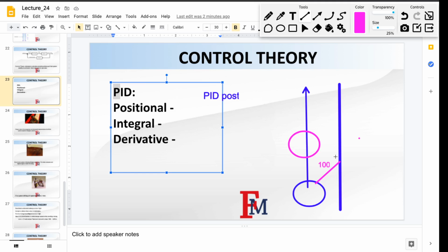Okay, and you're going to sense the wall again. So if you sense 125, for example, that means you moved about 25 to the left, right? So for some reason you moved over there, and that's not what you wanted. In this case, what are you going to do? You're going to take the difference, 25, and convert that difference into the speeds of the wheels.